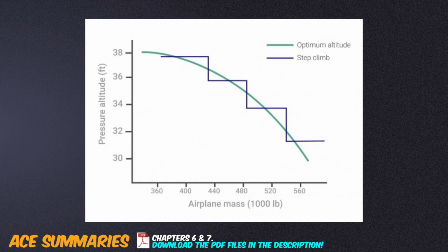A jet flight carried out below optimum altitude will burn more fuel, but it will take less time to complete when flying at constant Mach, because the local speed of sound is lower at higher altitudes. A set Mach number will correspond to a higher airspeed at lower altitudes.